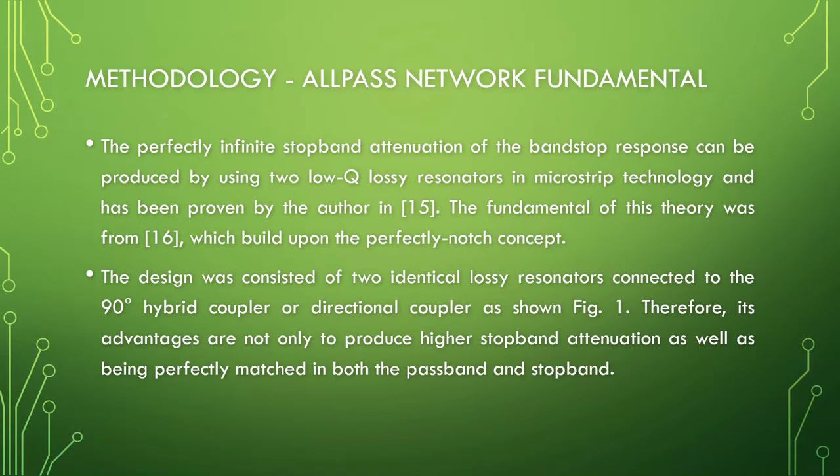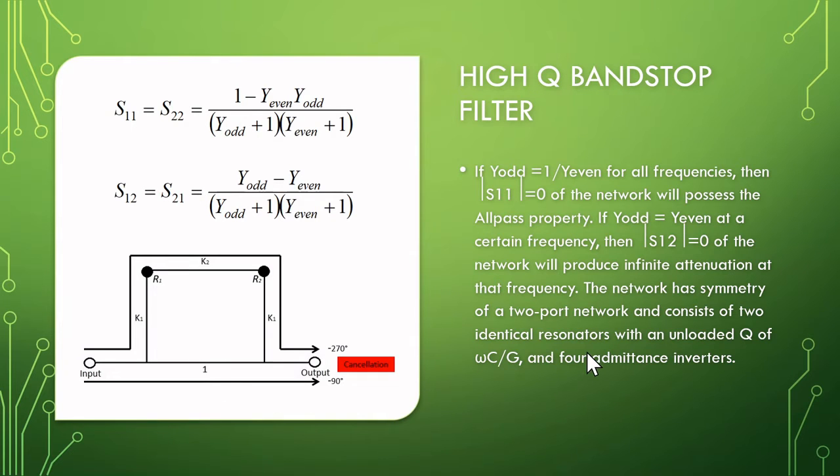The design consisted of 2 identical lossy resonators connected to a 90-degree hybrid coupler or directional coupler. Therefore, its advantages are not only to produce higher stop band attenuation, but also to be perfectly matched in both the band pass and the band stop. Let's move to the next slide.